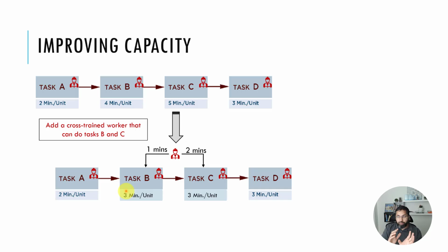So if you allow some WIP, even if task B and task C are a little bit far apart, there's some walking time, this worker can spend 2 hours at task C, then do 1 hour at task B, or 20 minutes and 10 minutes. So you can do this sort of split in time, even if you can't switch after every 2 minutes. Then you switch after 20 minutes or switch after 2 hours. But you still give the time in that ratio, and you use WIP to make sure no task is just waiting for a whole hour with nothing to do. And use some WIP in front of task C and in front of task B. And then that would allow you to do this. Okay.